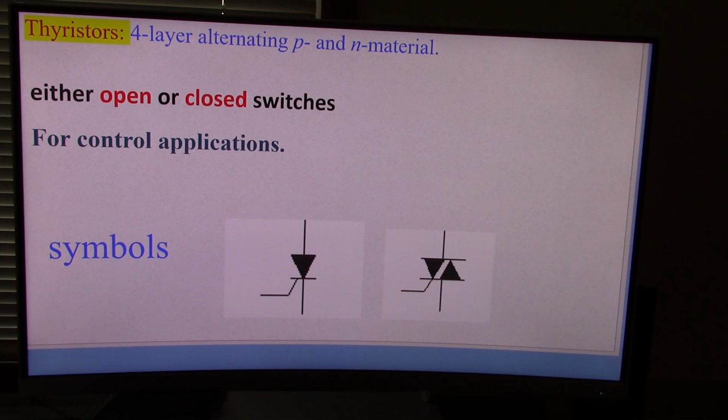And this is another kind of thyristor. This is called a Triac. If you look at this, it's 2 diodes back to back. The SCR conducts only when it is forward biased in this direction and there is a gate voltage. The Triac will conduct in either direction. So for an AC waveform, it will conduct for the positive or the negative waveform. The SCR, connected plus to minus like this, will conduct only during the positive-going waveform.